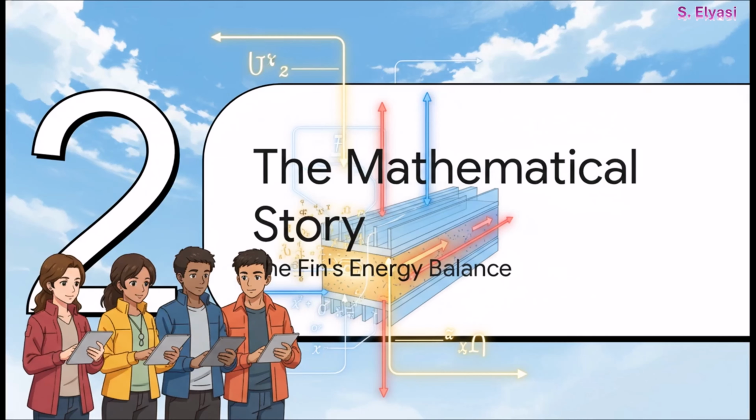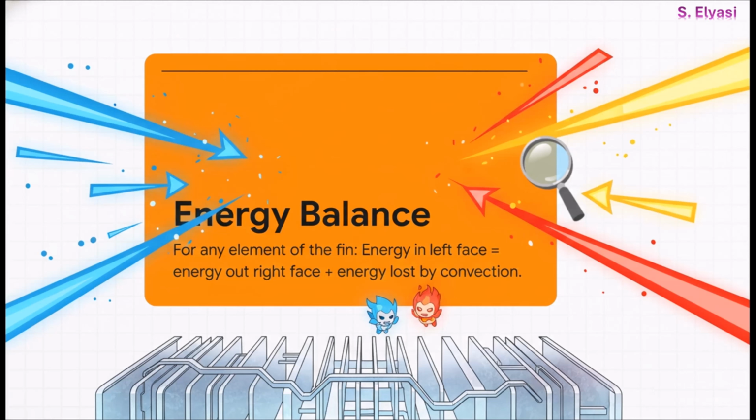So how do engineers actually figure out this balancing act? Well, like they always do, they tell its story with mathematics. And they do it by looking at a tiny imaginary slice of the fin and just watching what happens to the energy as it moves through. And this is all built on one of the most fundamental principles in all of physics: the energy balance. For any system that's running at a steady temperature, it is beautifully simple.